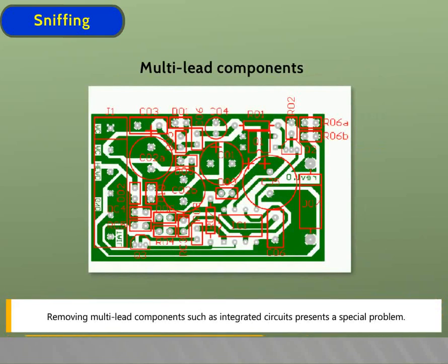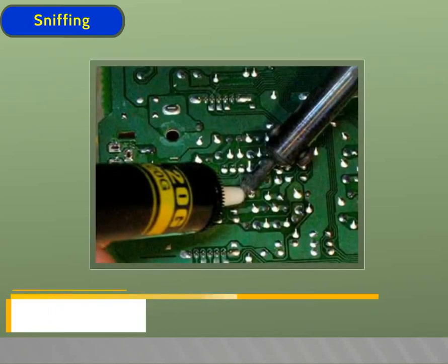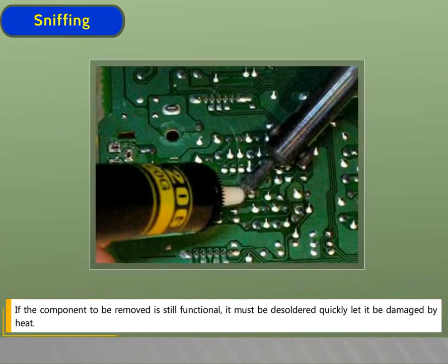Removing multi-lead components such as integrated circuits presents a special problem. If the component to be removed is still functional, it must be desoldered quickly lest it be damaged by heat.